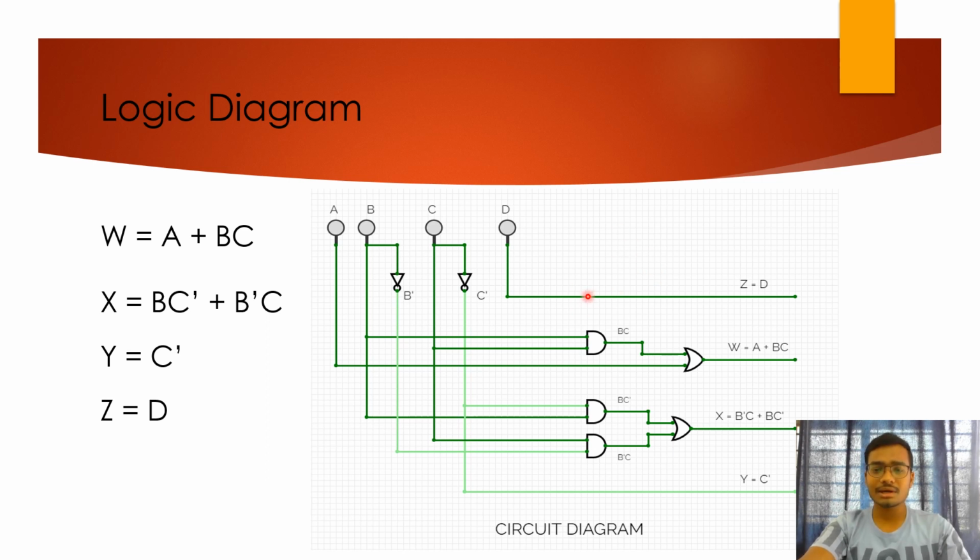Two NOT gates, it's like D, after applying a NOT gate, it will be giving me D bar, then D bar, upon applying the NOT gate, will be giving me D again. So there is no need to do all those things. We can just have D here. So this is what the 4-bit binary to Excess-2 converter logic diagram is.